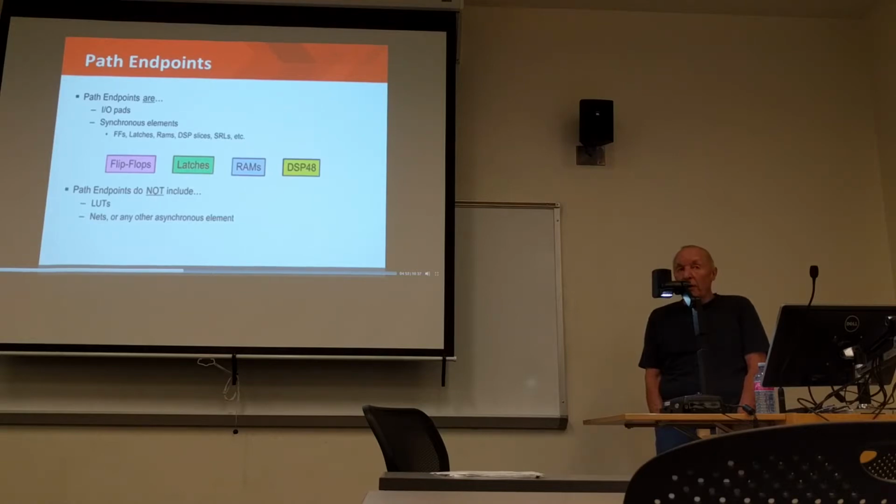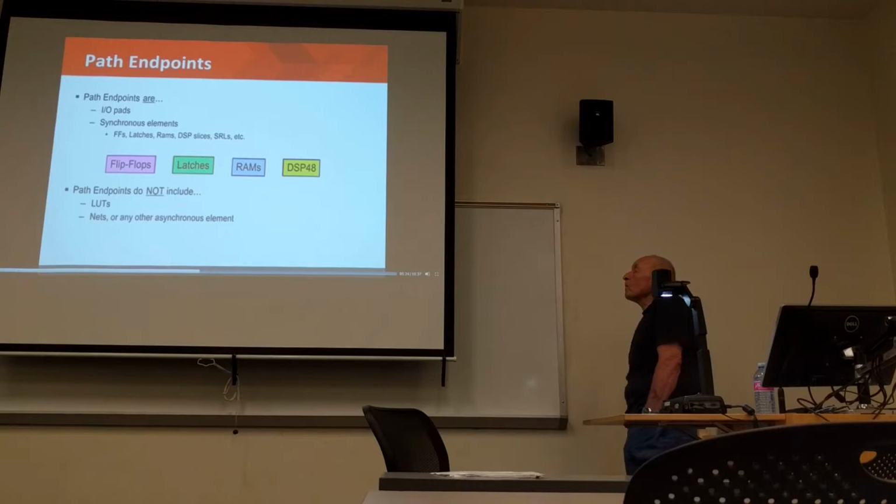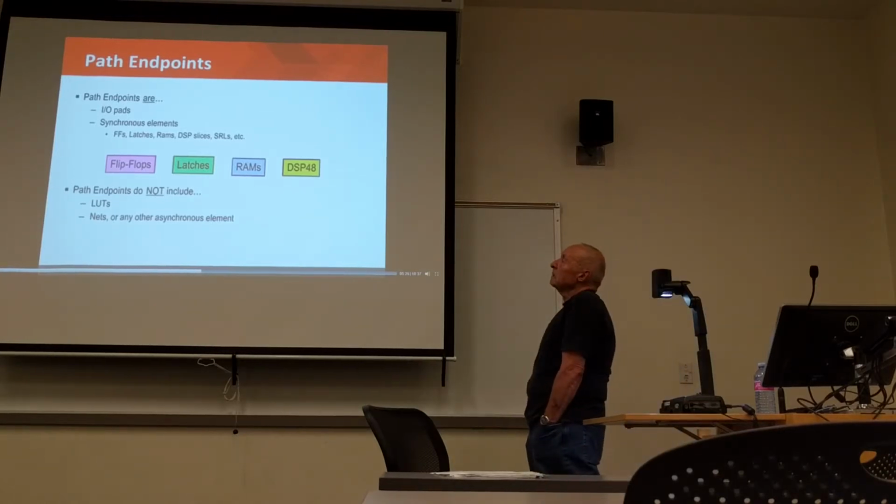Before we proceed to introduce you to the global timing constraints and the delay paths they cover, it's very important that you understand the possible path endpoints you can have. Once you start to understand how the implementation tools look at your design in terms of path endpoints, making the best timing constraints is very easy. While global timing constraints are very simple, understanding possible path endpoints is useful when you learn about path-specific timing constraints. Like global constraints, path-specific constraints are important to properly communicate your timing objectives to the implementation tools.